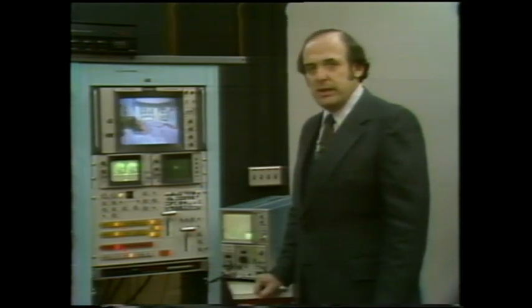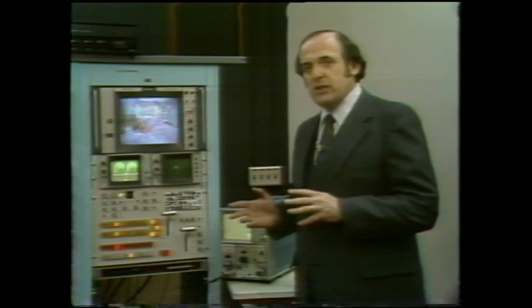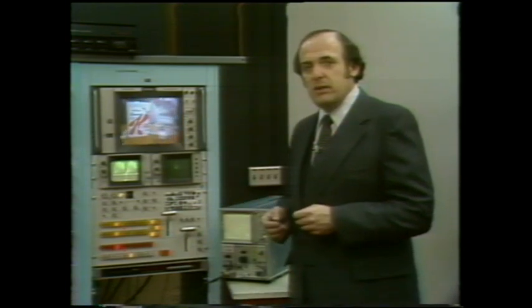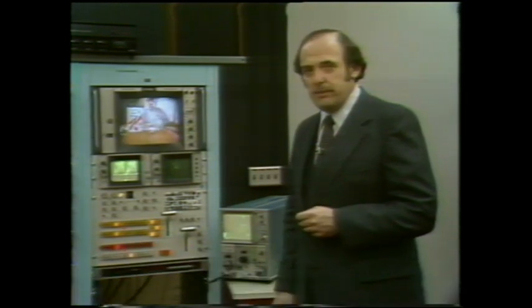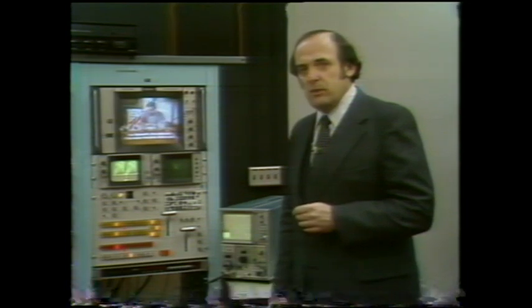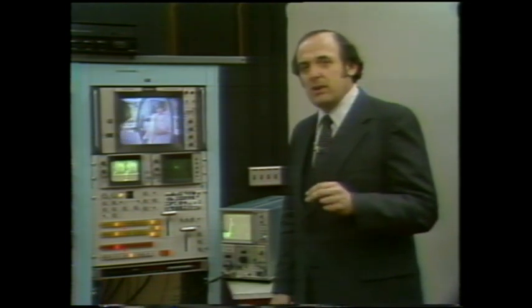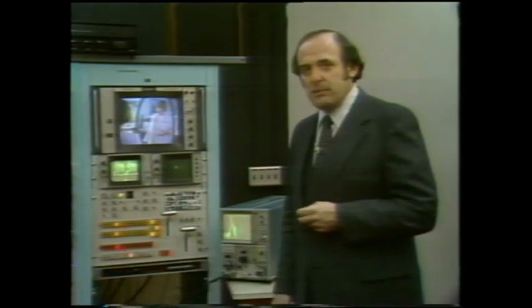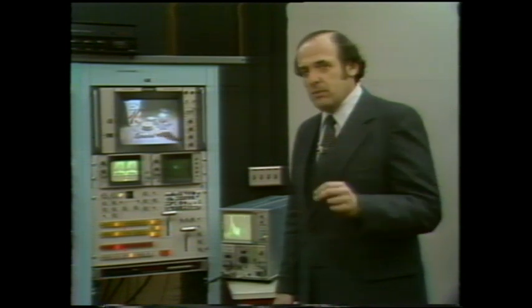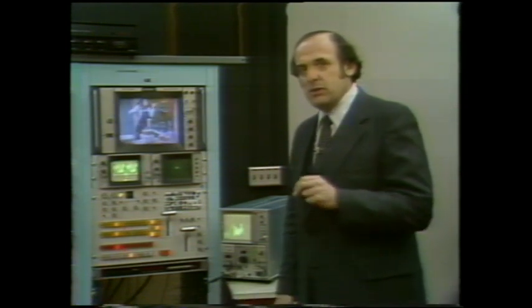Random noise occurs in nature. It's caused by thermal agitation of electrons, and it can be heard as hiss in an FM receiver. You have to remember when you're making noise measurements that noise bandwidth varies with individual applications. So be sure to normalize the bandwidth for your specific measurement. Techniques for doing this are found in 2 spectrum analyzer noise measurement application notes.